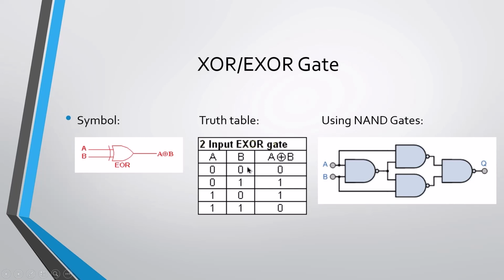XOR. The XOR, also called exclusive OR gate, acts in the same way as the logical either-or. The output is true if either but not both of the inputs is true, and the output is false if both inputs are false or if both inputs are true. Another way of looking at the circuit is to observe that the output is 1 if the inputs are different, and 0 if the inputs are the same.